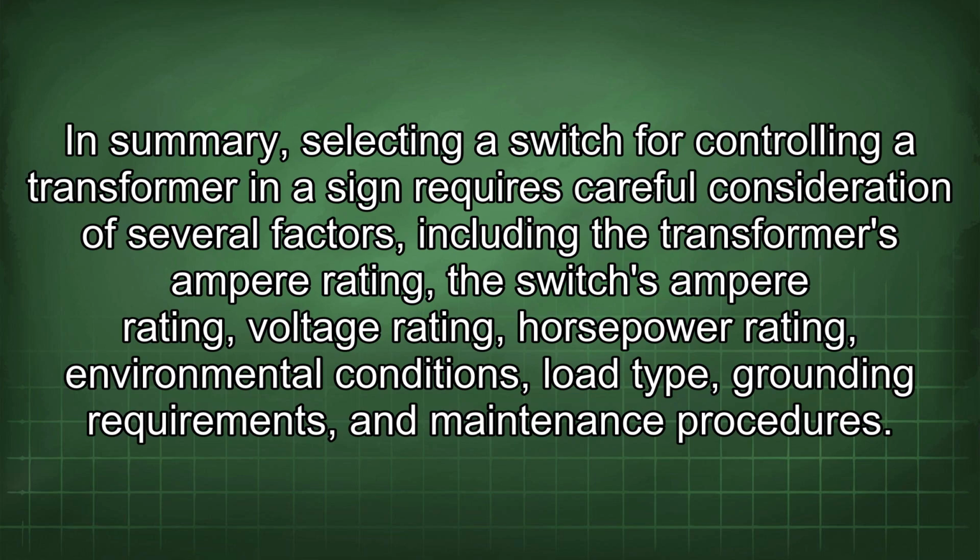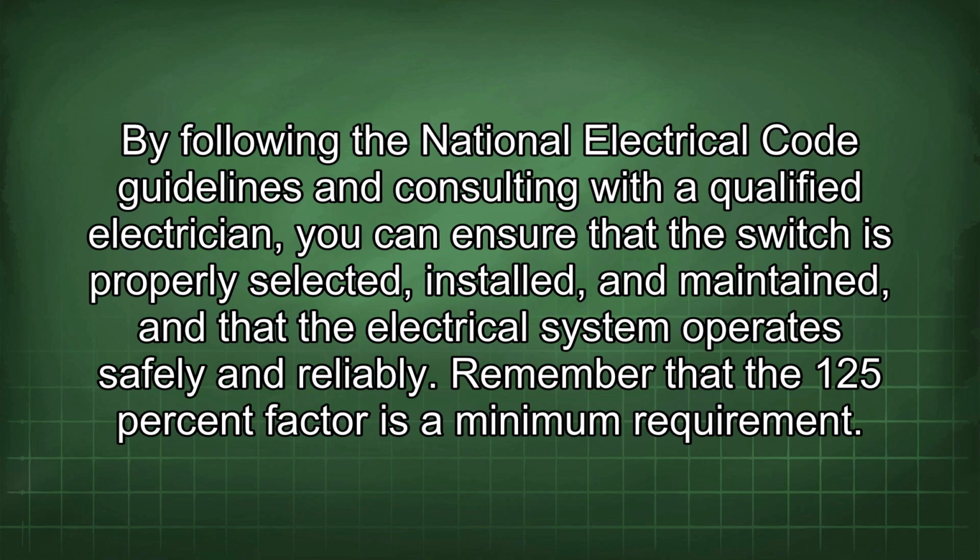In summary, selecting a switch for controlling a transformer in a sign requires careful consideration of several factors, including the transformer's ampere rating, the switch's ampere rating, voltage rating, horsepower rating, environmental conditions, load type, grounding requirements, and maintenance procedures. By following the National Electrical Code guidelines and consulting with a qualified electrician, you can ensure that the switch is properly selected, installed, and maintained, and that the electrical system operates safely and reliably.